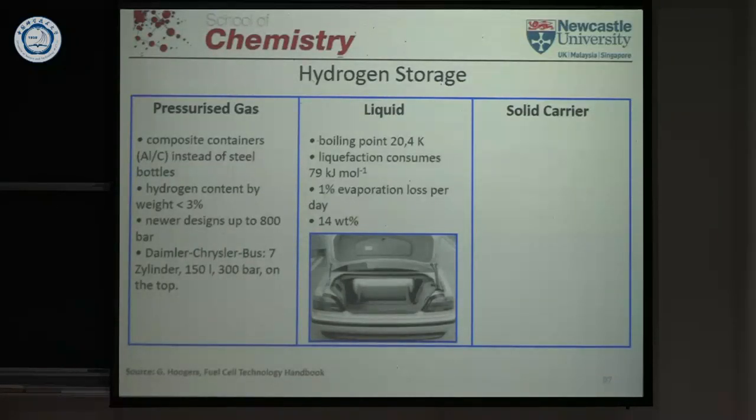And then, in addition to that, once you have brought it into the liquid state, you have to have it in a very well insulated container. And still you have some heat losses in that container, and the heat losses lead to a boil off of the hydrogen. And that boil off is about 1% of the material per day.